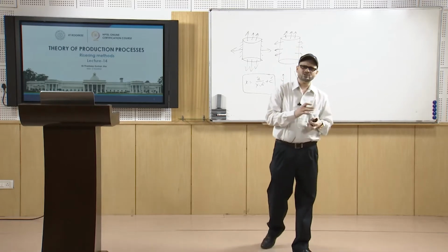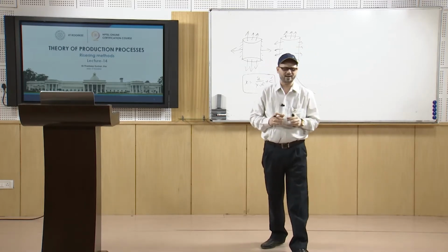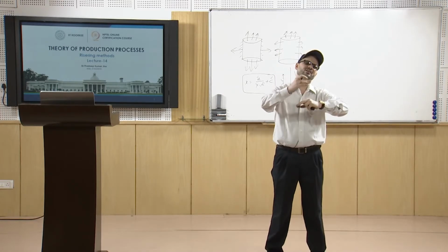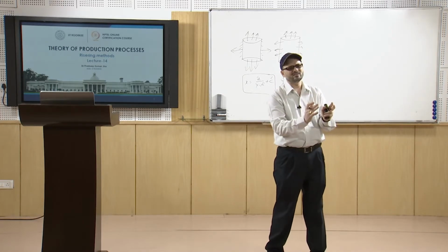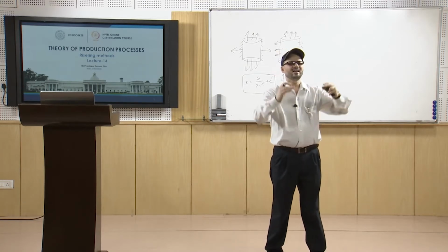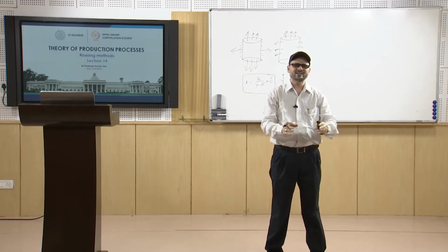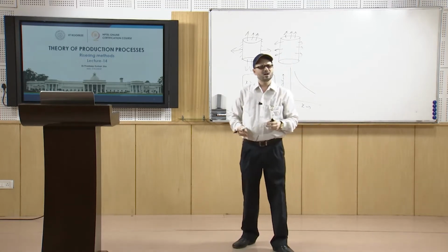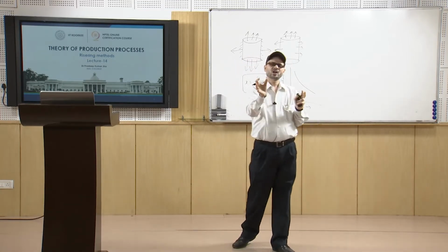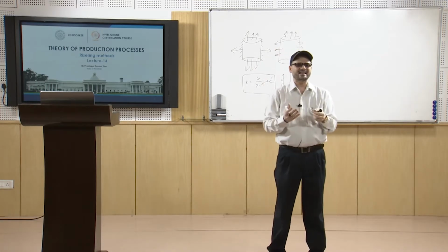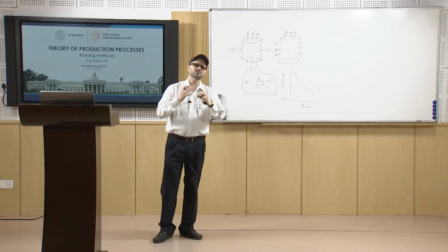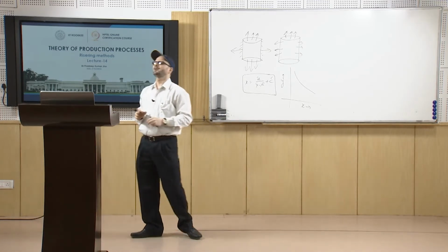Once you have that in mind, you have to consider what kind of appendage is there, whether the main casting is a plate feeding an appendage volume that is a bar, or the main casting is a bar feeding a plate, like that. In that case, that contribution has to be added to the total riser volume.